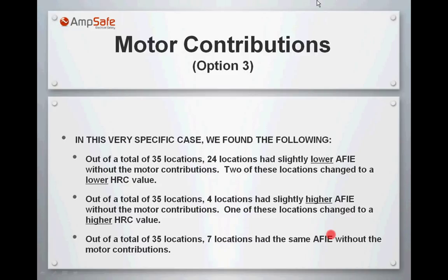Well, if you are an electrician working on an energized panel, and it happened that with the motor contribution, those few panels went up 1 PPE category, you might be affected. You would like all motors to be included, okay?